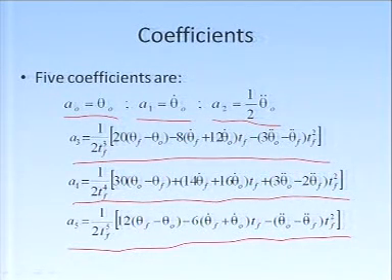So, sometimes we want to stop the robot with 0 velocity and 0 acceleration, and the same thing, we do not want to start suddenly. Assume somebody is pushing you from the back, wanting you to start running suddenly. So, there will be again a jerk, we do not want that. So, for those purposes we want to control the velocity and acceleration both at the beginning and at the end.